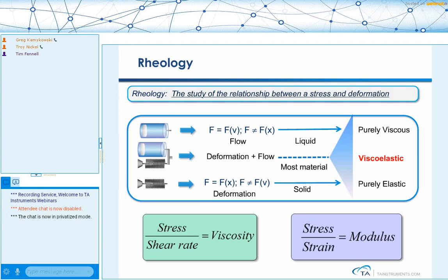When we say that rheology is the study of the flow and deformation of matter, we mean that when we look at flow properties, we're looking at how liquids behave, the viscous properties of a material. We illustrate that with this dashpot in which we pull a piston through a cylinder that has a fluid in it. What we know is that the force depends on the velocity at which we are pulling the piston, and it's independent of the displacement.